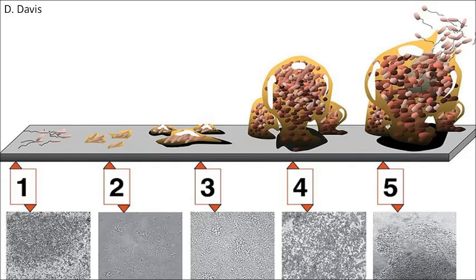And a biofilm is like a community or an aggregation of different types of microbes. So here we have just a collection of microbes, and they aggregate and form these complex communities. And the organic matter that's contained within the water feeds the biofilm, which allows it to grow. And then usually most water treatment facilities will use rotifers or nematode worms that will graze on the biofilm to keep it healthy, and they allow the bacteria in the biofilm communities to continually be replenished. So it's sort of like a self-cleaning filter in this sense.